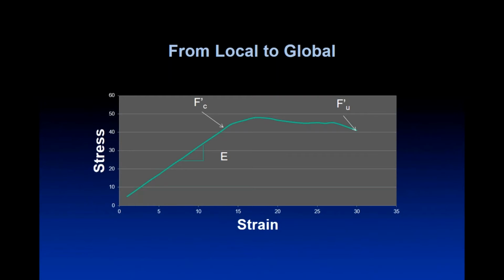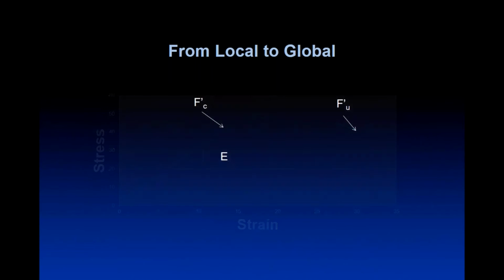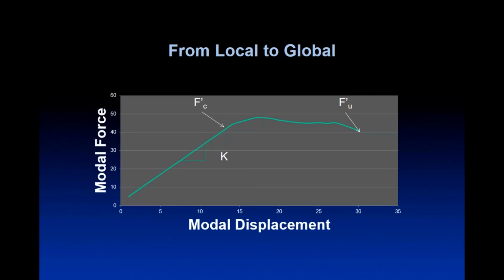In California, for instance, they say that the drift, the relative displacement between floors of a structure, must be within a certain limit. If we're talking about human perception of vibration, then we've actually got some other criteria that are used for whether people are going to feel comfortable. You don't want to be in your room, sitting down, watching a TV, and finding that the whole thing is moving around, coffee cups rattling or whatever.